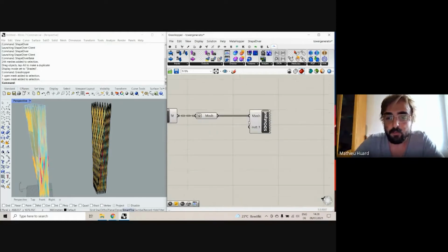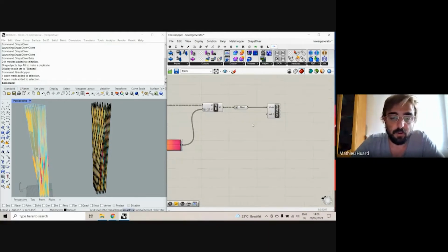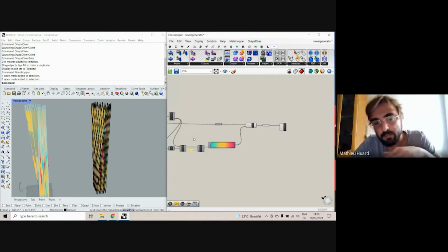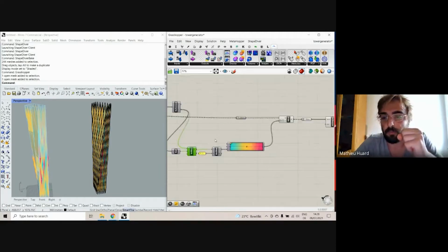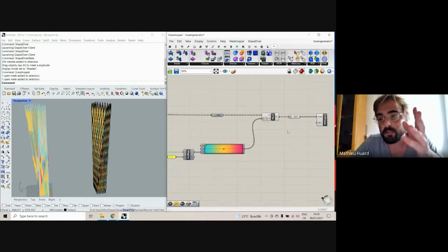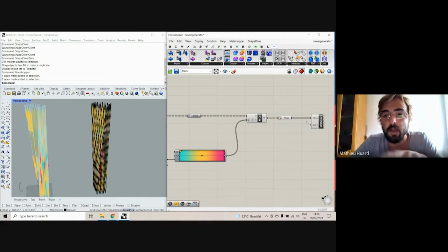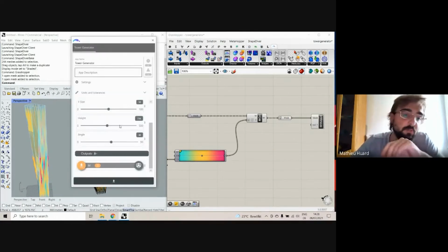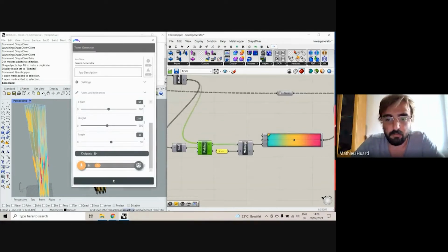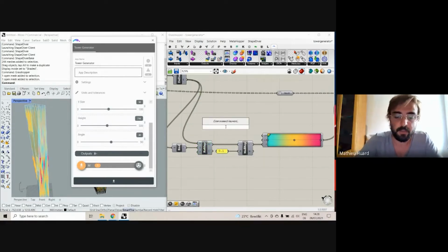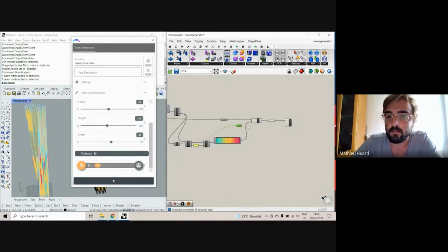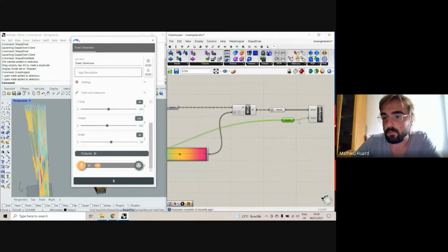Which means that I also somehow need to send this data that I want for my second algorithm. And I can do that in several ways. I mean, really, the inputs and outputs of a Shapediver application can be really any type that exists in Grasshopper, almost, not all, but almost. So if here I want to send, alongside my list of meshes, a list of numbers.